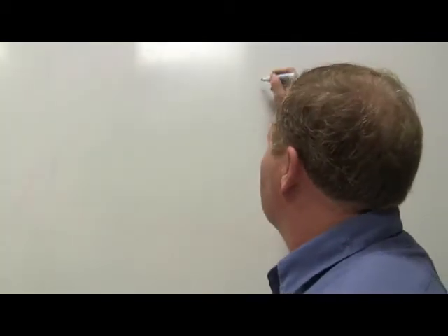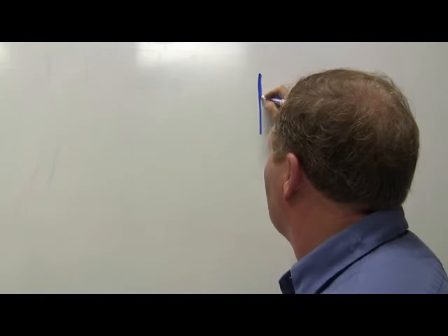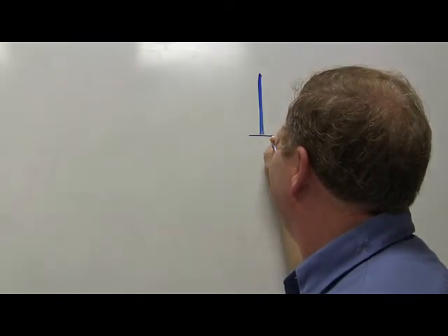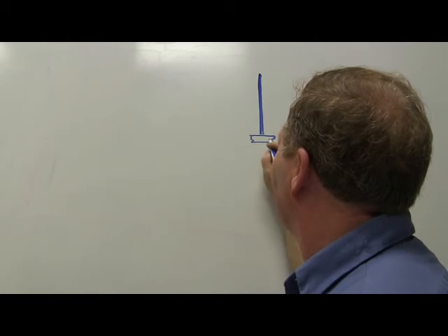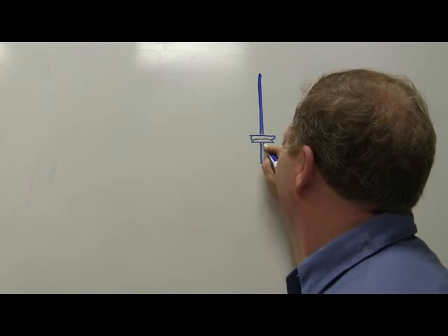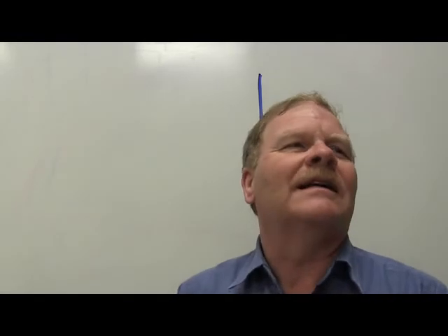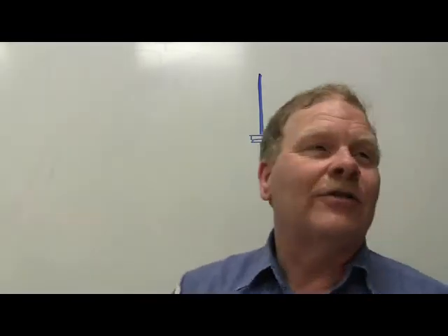However, how many of you have seen on a Chevrolet wiring schematic, on a General Motors wiring schematic, something that looks like this? And I may not be drawing it exactly right. You'll see that on a GM wiring schematic, and what that means is that the wire passes through the bulkhead.